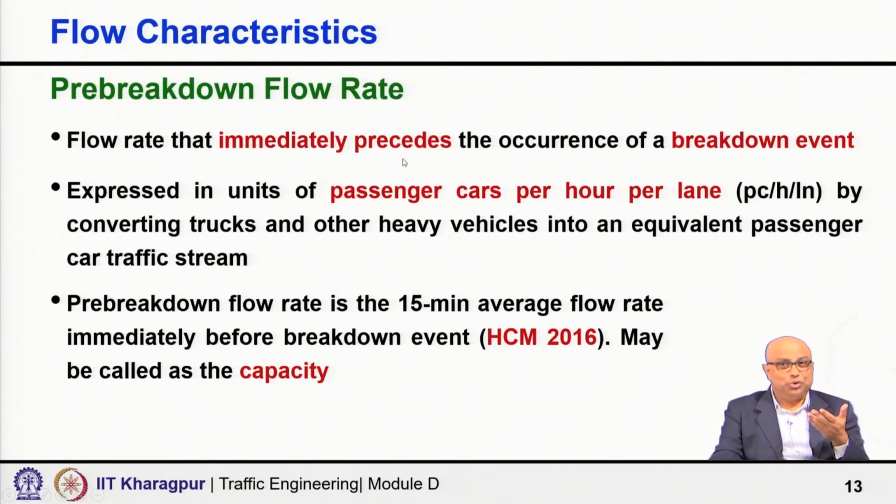Now, the pre-breakdown flow rate: before it breaks down, what is the flow rate? It is the flow rate that immediately precedes, carefully note it, the occurrence of the breakdown event. The demand is going up and there is a bottleneck. It is expressed as usual in units of passenger cars per hour per lane.